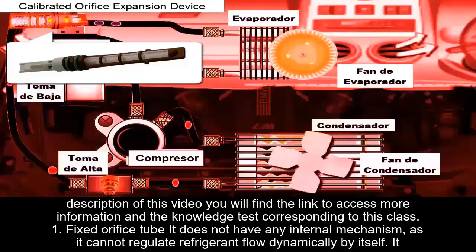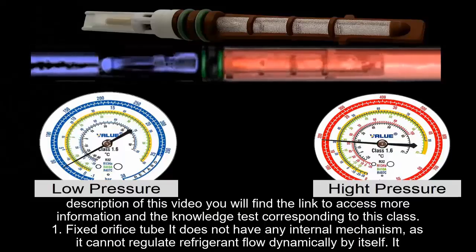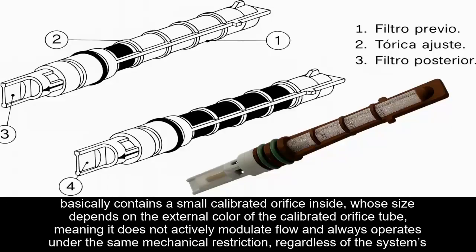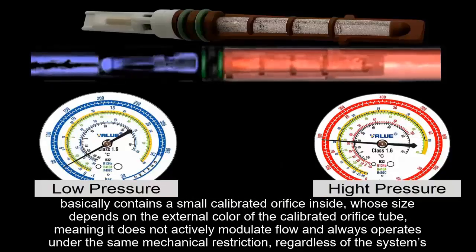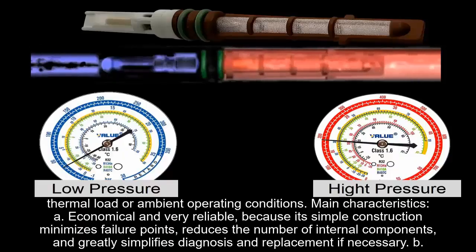1. Fixed orifice tube. It does not have any internal mechanism, as it cannot regulate refrigerant flow dynamically by itself. It basically contains a small, calibrated orifice inside, whose size depends on the external color of the calibrated orifice tube, meaning it does not actively modulate flow and always operates under the same mechanical restriction, regardless of the system's thermal load or ambient operating conditions.